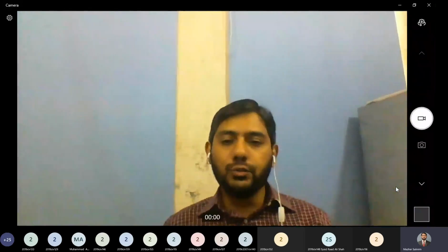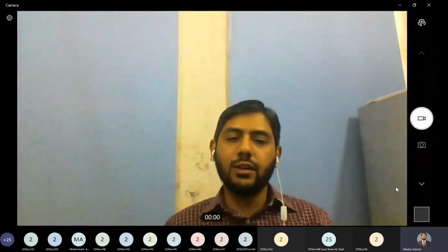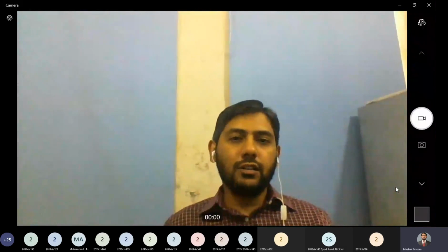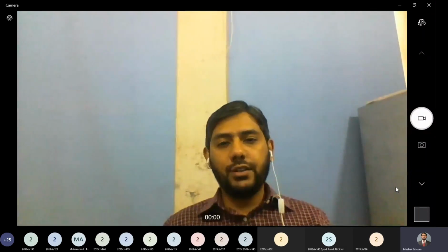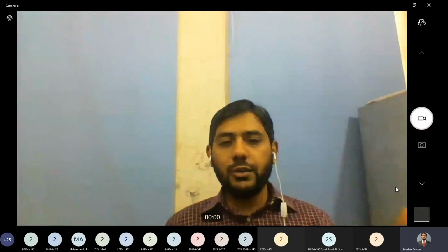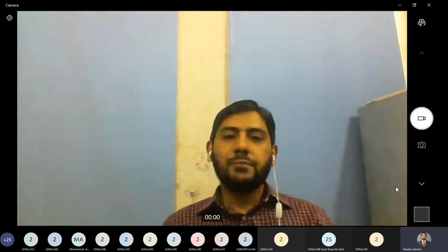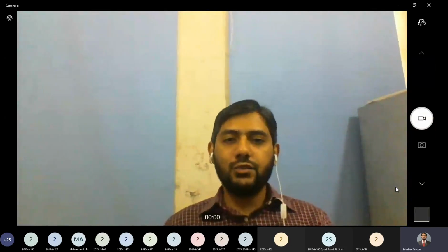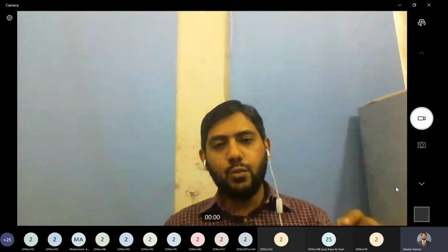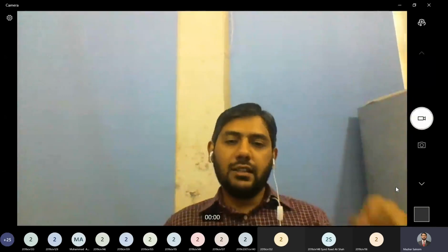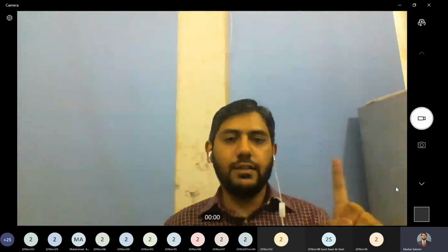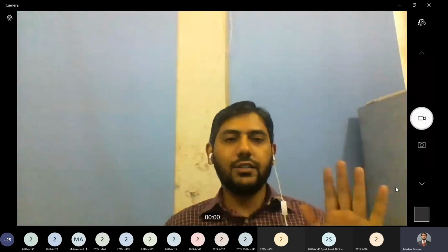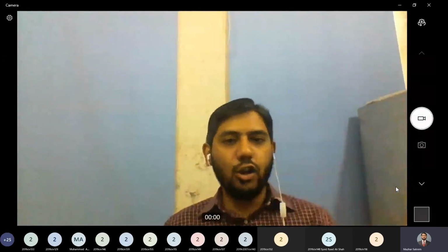So it's up to you as an engineer. If you are analyzing a problem, it is your understanding of which point you want to measure deflection at. Wherever you want to measure, you will install the dial gauge. And if your question is whether it gives us deflection for a particular point or for an entire member, then the answer is that it gives us deflection for a single point. It does not give us deflection for the entire member for all the locations.